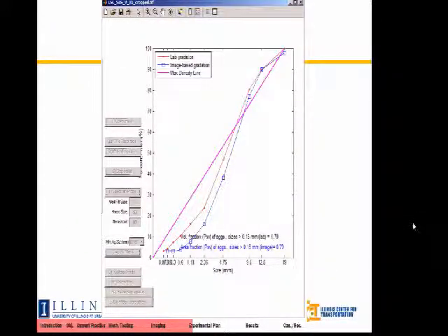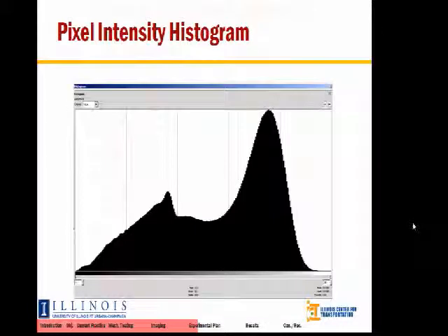Just showing that appropriate processing steps were accomplished. Okay? Very nice agreement between the image-based gradation and the known laboratory-based gradation, as well as volume fraction versus area fraction in this case. So this is just one screenshot of the study. You can use nearly any imaging software to capture a simple pixel intensity histogram. Okay, so after the processing phase, when this image becomes grayscale, so again, doesn't matter what device you use to capture it, you're converting this image to grayscale, and we're looking at the pixel intensity.